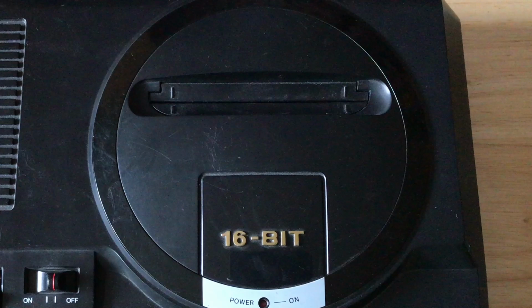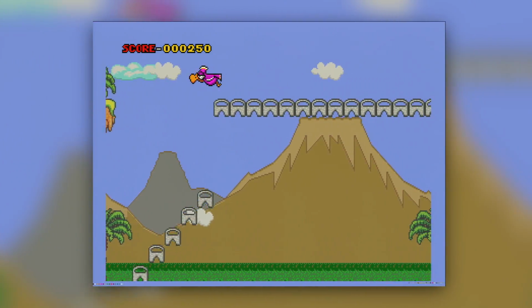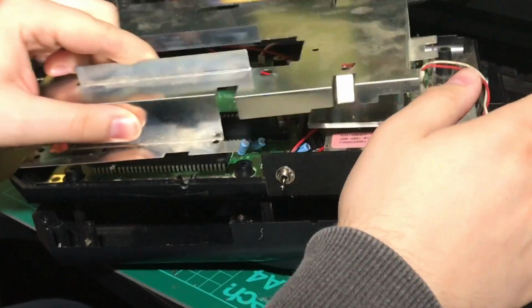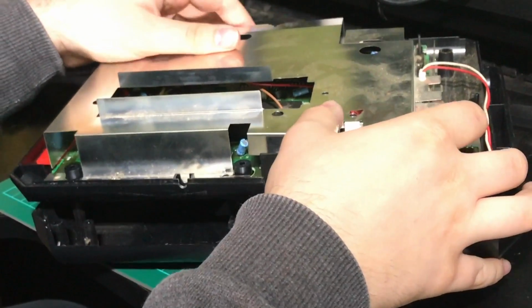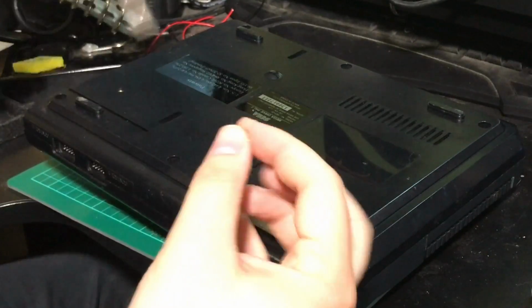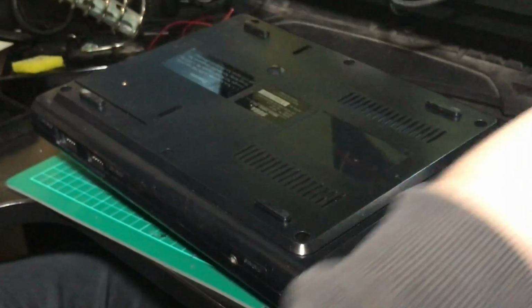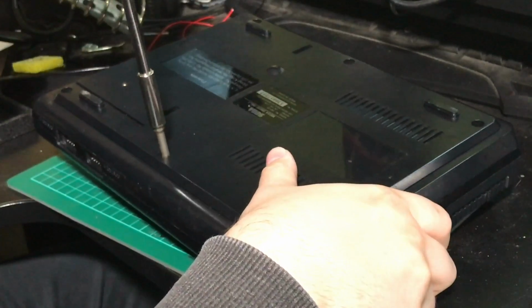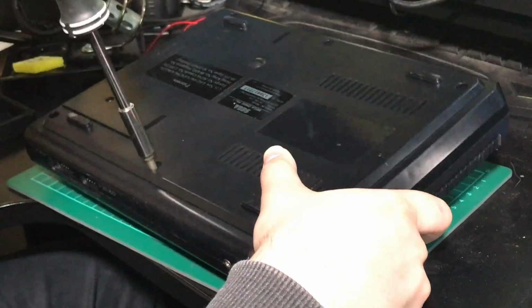If you want to play Japanese games without a slot converter, you'll need to remove these corner tabs on your cartridge slot as well, but as someone who uses flash carts like the EverDrive, I personally don't find it necessary, and it's a little ugly as well. Now you can put the whole thing back together. Put the metal shielding back in place, screw it in, and then put together the casing. If you removed the LED assembly, make sure you reinserted it the right way with the correct wires leading to the correct LED pins. It's also worth making sure that the headphone jack's volume slider's position on the board matches up with the position on your shell, otherwise you'll feel very foolish when you put it all back together.